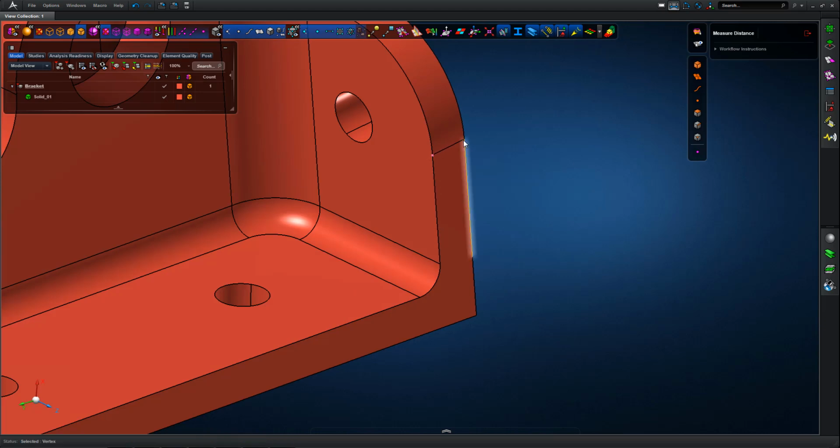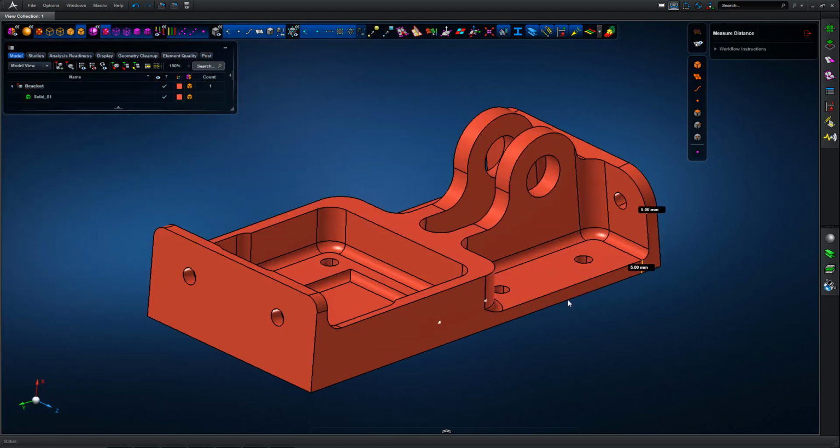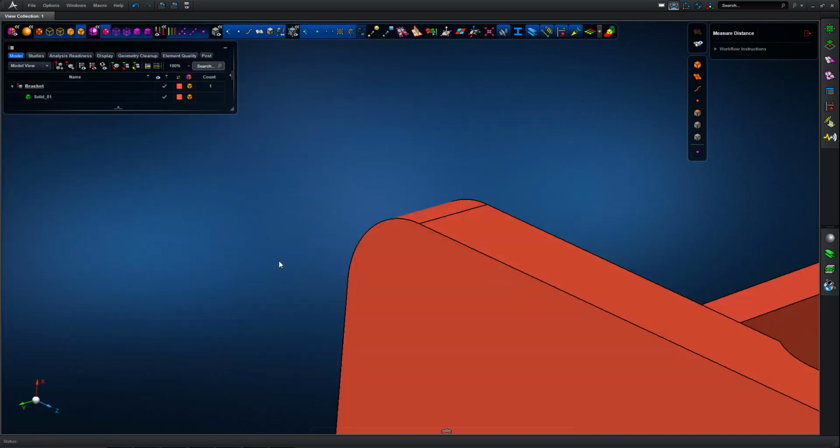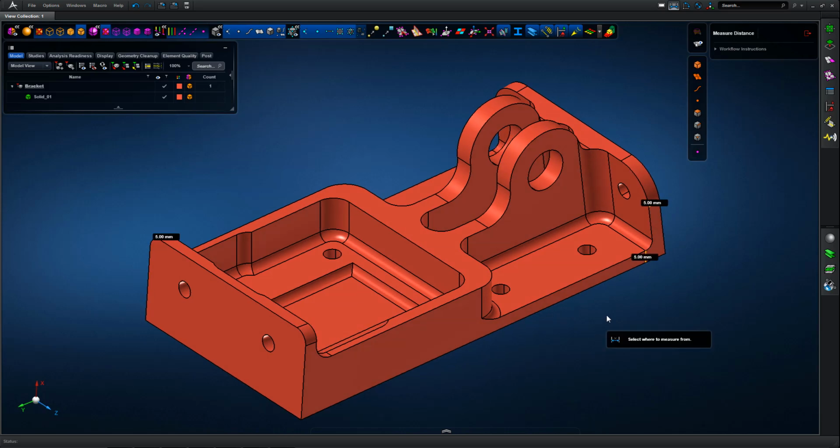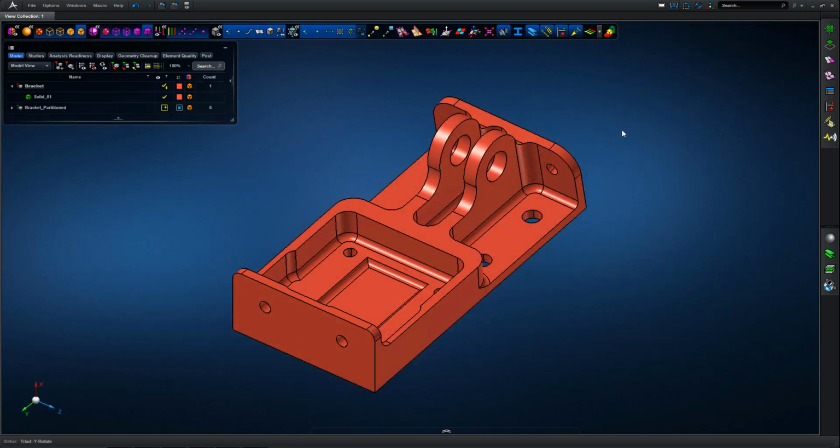So first of all we're just going through the model, measuring the wall thicknesses. So we can see we've got a standard 5mm wall thickness for the thinner regions, so that will enable us to guide the downstream Tet meshing geometry or Tet meshing size.